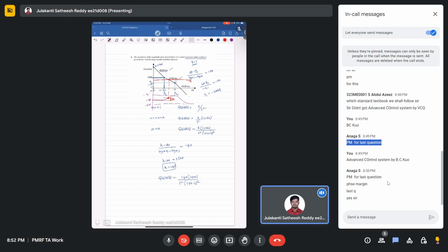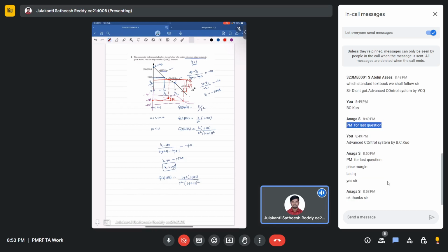Now you see exactly at this frequency it is minus 180, right? So this entire line is minus 180, so we don't consider it. Next, you see again the minus 180 line is touching at this point. Now you draw this line close enough to this. With respect to this, you see this is the gain margin, so this difference you need to find. If both are positive, you can say it is stable. If it is negative, you can consider that. Okay, it's only for understanding the concept.